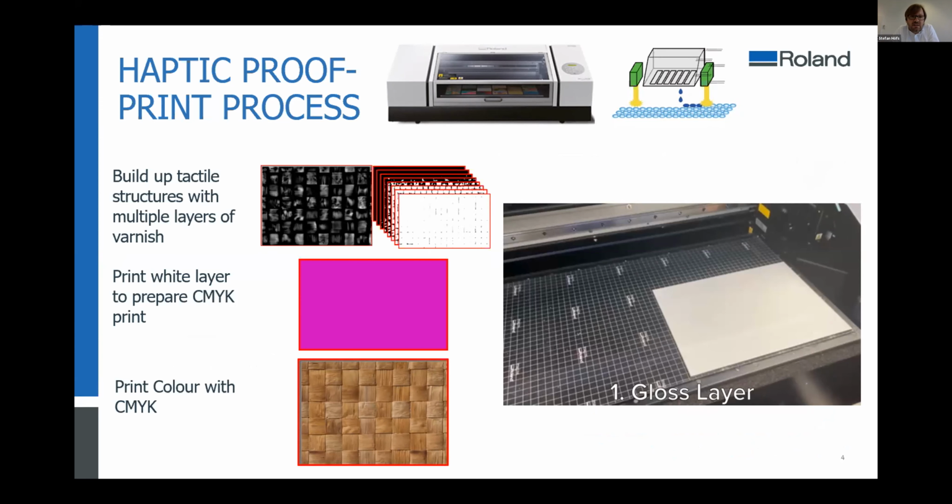First file is the black and white image presenting the height profile of the surface of the scanned object. For us, it's important that white is representing the height 0 and black is representing the maximum height. And the second file we need from the scanner is the high resolution RGB file that contains all the color information.